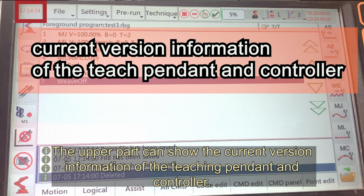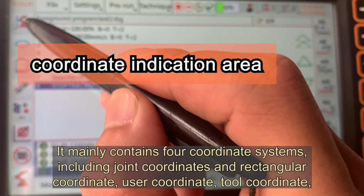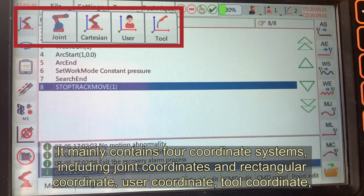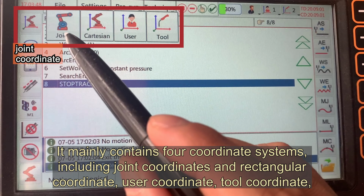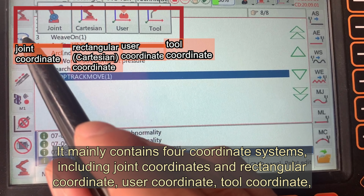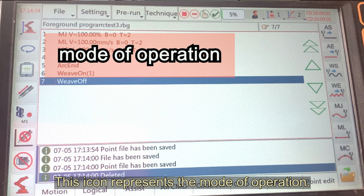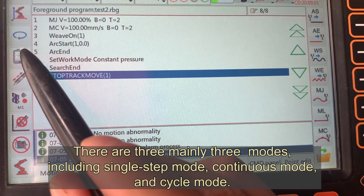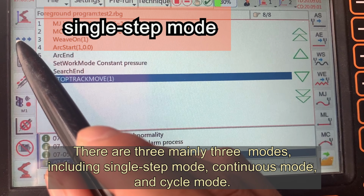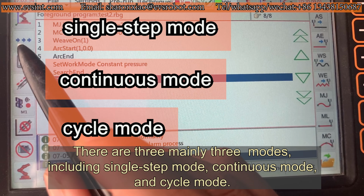The upper part shows the current version information of the teaching pendant and controller. This button is the coordinate indication area. It mainly contains the four coordinate systems, including joint coordinate, rectangular coordinate, user coordinate, and tool coordinate, and the coordinate modes can be switched here. This icon represents the mode of operation. There are mainly three modes: single-step mode, continuous mode, and cycle mode.